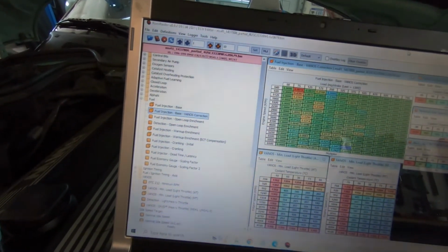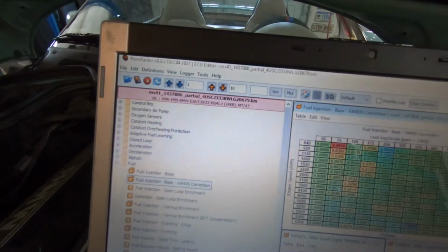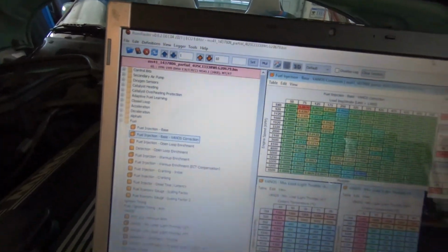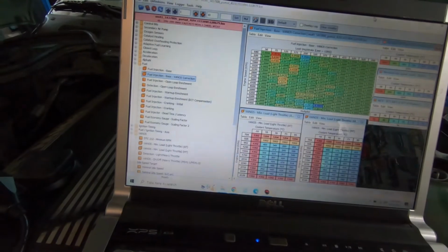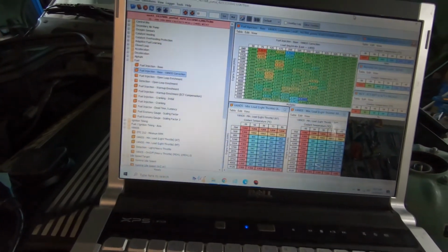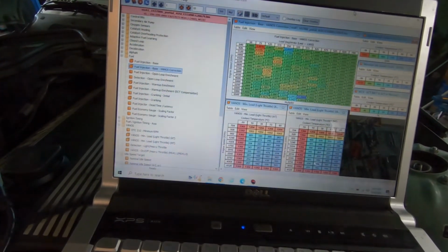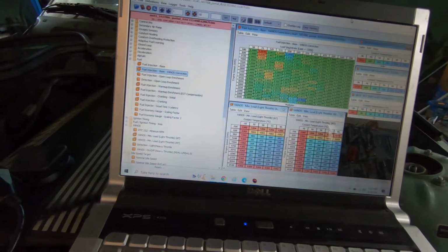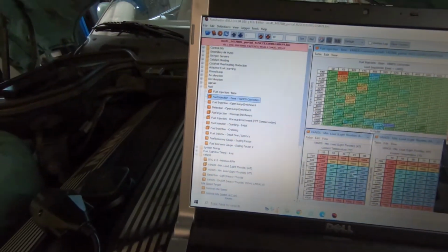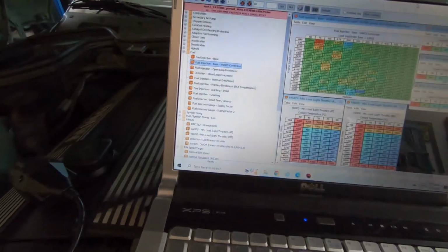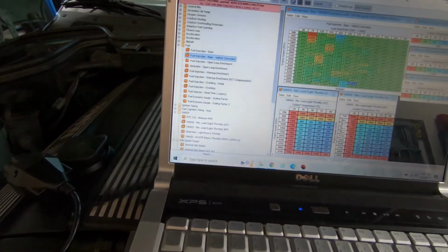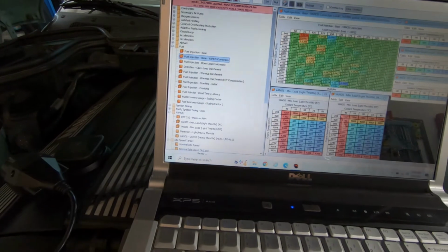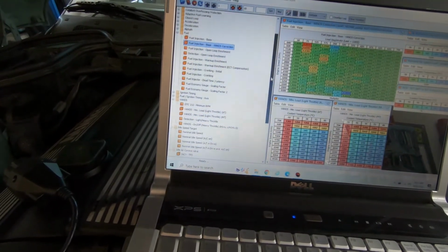The engine control module just needs to know which one of those transmissions it is, and it'll follow the appropriate calibration set based on that input. So that's why we're trying to tell the engine control module that it's a manual transmission car now. I tried to pull up on the left side here a few things that appear to be affected by manual versus automatic.